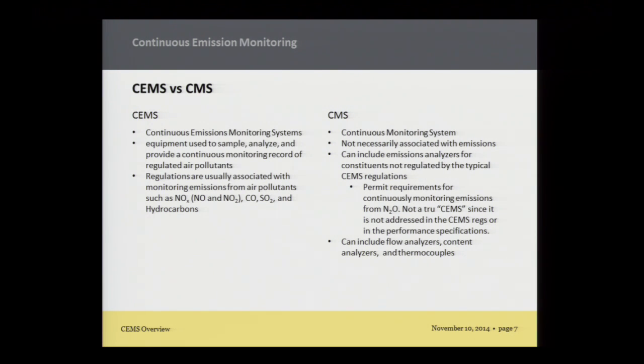And the CMS is a continuous monitoring system, and it's not necessarily associated with emissions. It can include emissions analyzers, and typically there are permit requirements for continuously monitoring emissions for N2O, but it's not a true CEMS. It's not addressed in the CEMS regs and does not have a performance spec. And it can include such things as flow analyzers, content analyzers, and thermocouples.